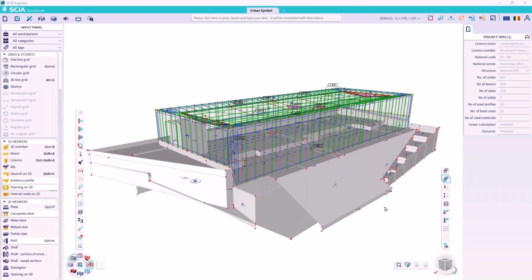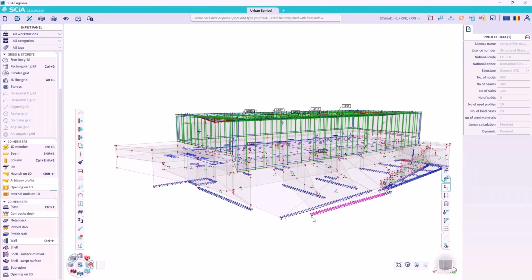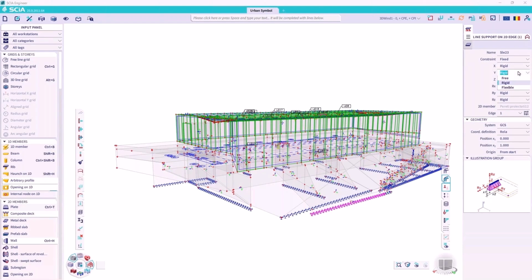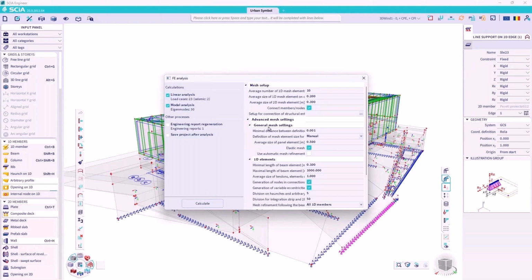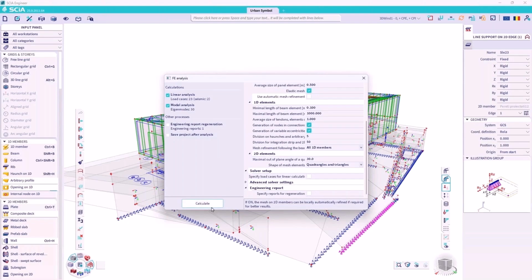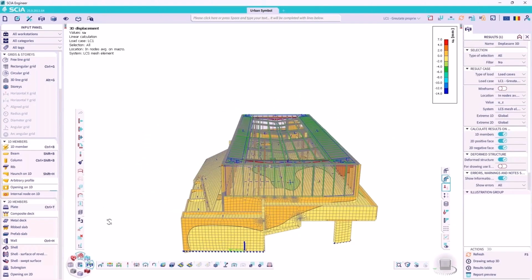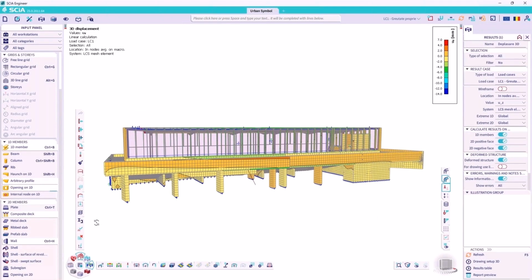So let's see exactly how it works. So once we got the aligned model from the SAP file, we can now assign some supports and we can run quickly a self-weight analysis. So we can control this support, on each of the 6 degrees of freedom, to be rigid, flexible, or have a non-linear behavior and so on. So we'll run now the analysis and make a check from self-weight to see how it looks. So to make sure that we don't have any kind of singularities or mechanism, to make sure that the model that we imported from the automatic alignment actually works.